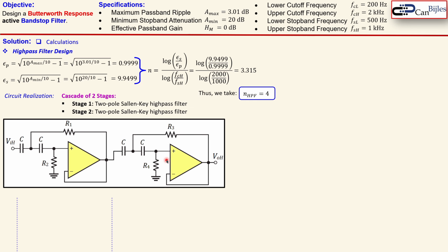And that's actually shown here. You see the two stages here, stage 1 and stage 2. And the gain configuration for this operational amplifier is 1. So you see here the buffer, so you will get 0 dB gain.